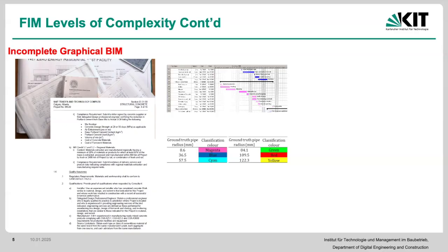For that, you can use some natural language processing on the technical specifications of the particular project and then extract that baseline information. Okay? This is where I'm saying that the complexity of the problem arises and the information modeling arises, as the incompleteness in 3 important aspects also changes. One of them is the design or the planned information. The other one is whether we have construction errors or not. And the third one is the instrument itself that we're using for the collection of data. In this case, we're going to give the example of point clouds because that's what we're going to be working with a bit more and it's a bit more tangible. But there are other types of information that you can collect as well, right?